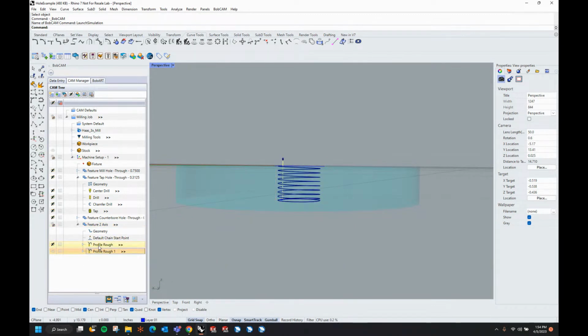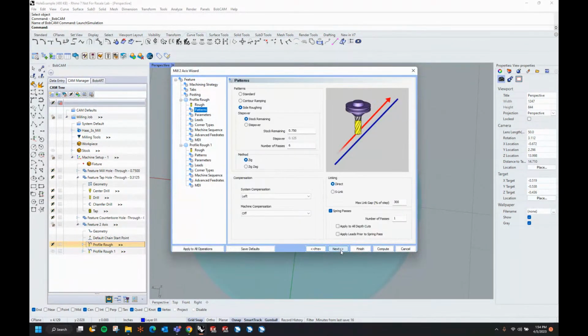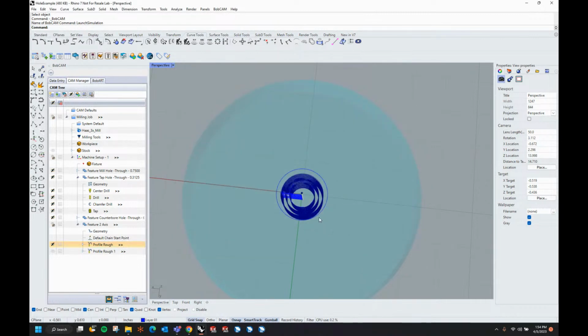There we've got our spiral down, and then our side roughing coming in. So I need to adjust that side roughing. Holy cow. It's actually 3/8 per side. That's right. 3 passes. There we go. That's what I wanted to see. I overdefined it. I gave it total, not per side.